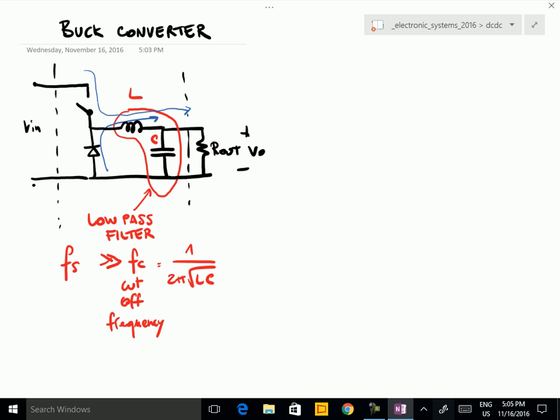So typically it is sufficient that the inductance puts this voltage down to 0, so that the diode starts to conduct, is turned on, and the current can flow in this direction. So the diode avoids any voltage spike on the switch, because as soon as the voltage on this point goes to 0, the diode is turned on and current can flow.